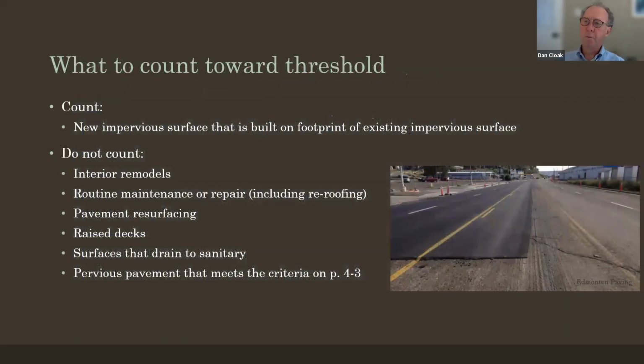Often these come in the terms of what to count towards the threshold. And this is often a source of some confusion. Yes, impervious surface that is built on the footprint of existing impervious surface does count towards the threshold. So if you're redeveloping a site and you say, well, it was already impervious, I'm making it less impervious than it was before, the treatment requirements still apply. Because the criterion is what you built.